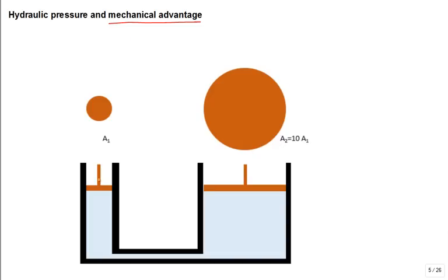So here we see the mechanical advantage of a hydraulic system. Think about a piston connected to a fluid system. The piston over here has a small area, A1. Over here it has a large area, A2. So if I push down with a force F1, doesn't it increase the pressure underneath the piston? I'm just thinking of pressure increases. The increase would be force 1 divided by A1.